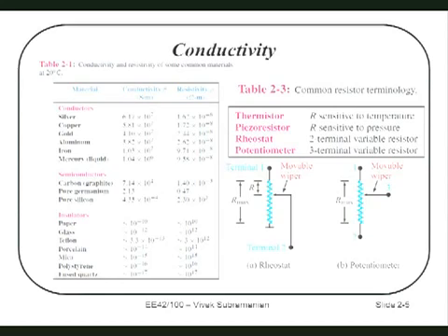It turns out, and that, by the way, is related to the comment you made earlier, most electrical insulators are horrible thermal conductors. This is good and bad. The plastic you coat your wires with is a bad thermal conductor. So it's also a bad electrical conductor, but if the wire gets hot, there's no way for the heat to escape. That's good because when you touch the wire, it doesn't burn you. But it's bad because the heat keeps building up until the thing actually catches fire. That's actually kind of a problem. Yeah, question?